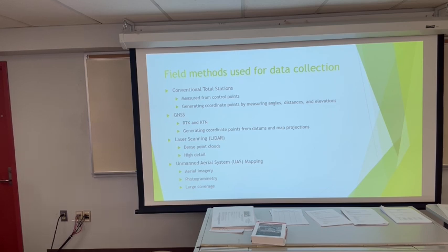RTN, real-time network. Particularly in Ohio, most people would say using the VRS, virtual reference station. That's where you're just using a receiver only. You're connecting a modem to the internet and you're receiving CORS information directly online.